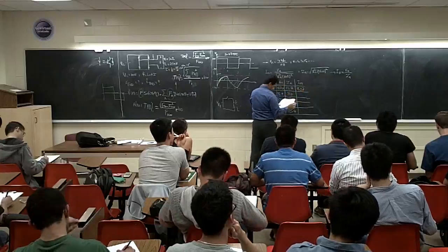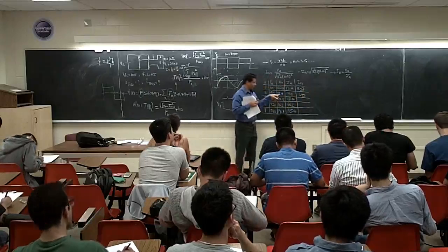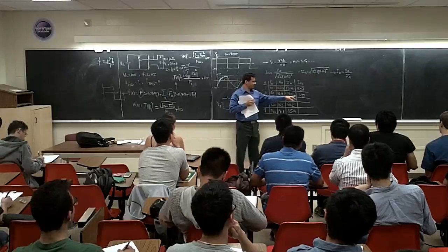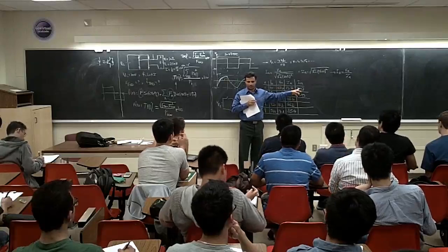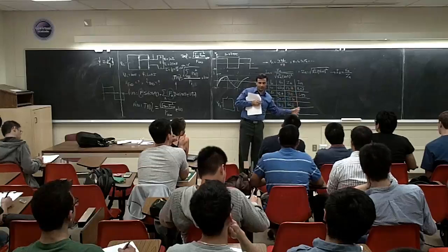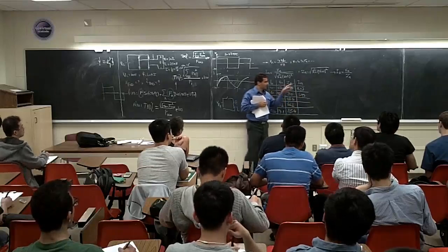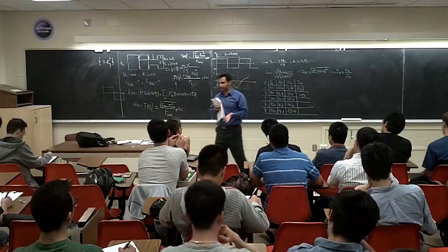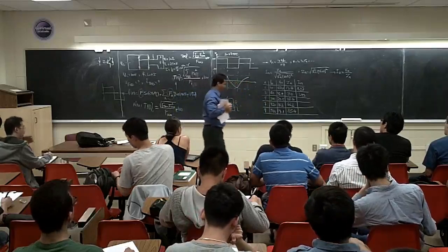These are all amps. This one is going to be 1.42. Look at here. Compare this one with this one. This is almost 1/3, right? How much is this one? Something like maybe 10%, 12%, 13%. It is much better, right? You can see already the harmonics of the current looking better than the voltage. Why? Because we have L in this circuit. Remember we said L is a filter, it's going to clean up the current. You can see here what it's doing also. It's cleaning up the current.